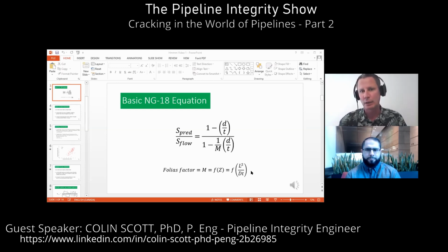A lot of people should be familiar with this, particularly if they're in the corrosion business, because this is the basis of B31G. If you look at those models, they'll typically have other factors in there. Original B31G has a 2/3 factor, and modified B31G has a 0.85 factor, but essentially this is just the bare bones of it. So I'm hoping that your viewers will be somewhat familiar with that. Yeah, I think anyone who uses the corrosion models will recognize this right away.